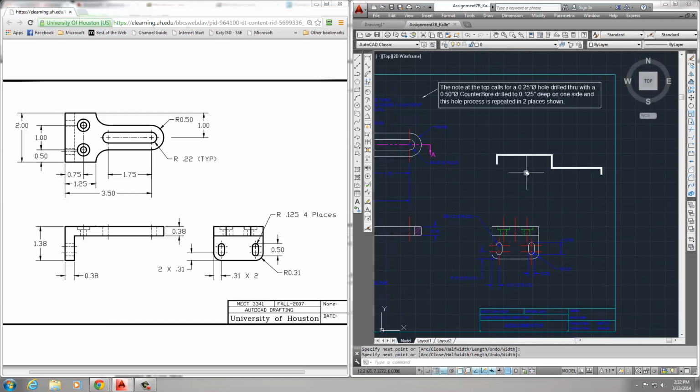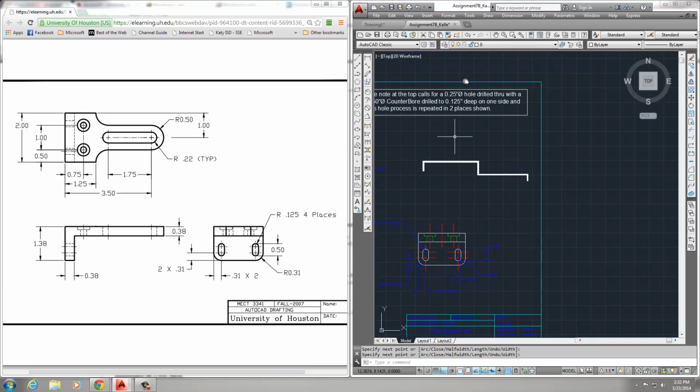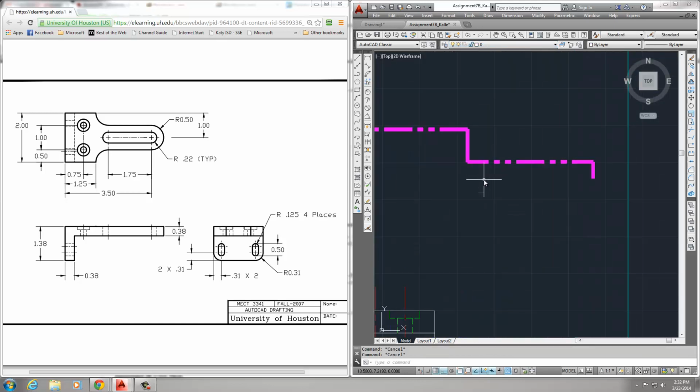Okay, so number one, also the line type that's used for section cut is a phantom line. So make sure you pick phantom. So right now I've got phantom here for section line. So I'll pick this, and I pick phantom for section line. And there it is. So that's how you get that big line that you did.